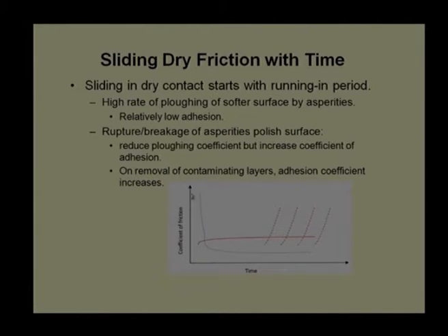One pair can show life is starting, coefficient of friction is decreasing, reaching a steady state condition, and then again coefficient of friction increasing. Another similar component, a similar material pair, in another condition it can show reaching this condition, moving to a straight condition, and finally ending with this line. It depends on environmental condition which line will be selected, or there is a possibility of extended life, or many times we get infinite life. That is also a possibility of infinite life. It will show coefficient of friction as a steady value throughout its life. There is a possibility.